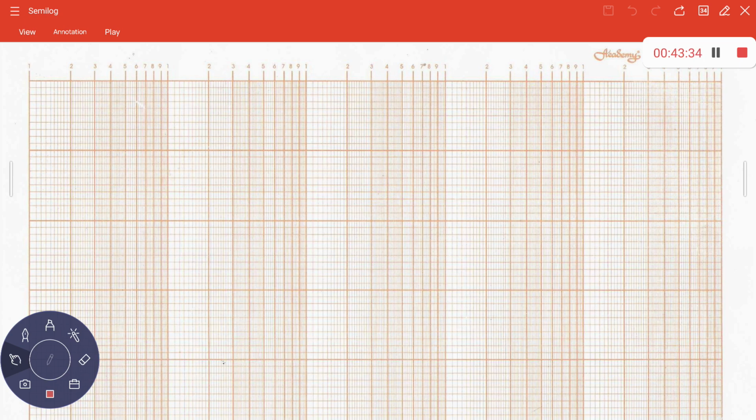Log base 10 always. For the dB scale, the voltage gain we have already calculated. In the dB scale, 20 log of that gain will give you the gain in dB. The ratio is basically Vo by V in, and if you take 20 log of this ratio gain, it will give you the dB gain, right? Decibel. So whenever I say log in this class, that is log base 10.